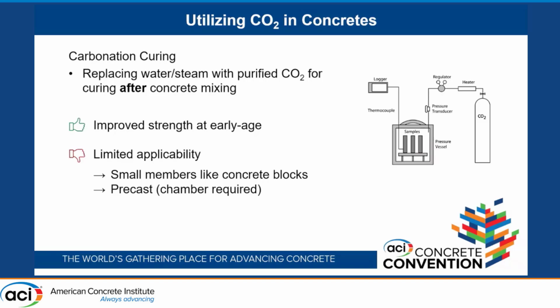Now, there are a couple of different ways that the industry utilizes this CO2 sink. The first way is through carbonation curing, where the curing water or steam is replaced with purified CO2 and is used to cure the concrete once it's been molded. This gives improved strength at early age stages for the concrete. However, it has limited applicability. It's used mostly for small, non-reinforced concrete blocks, and it can only be used for precast concrete, not ready-mix concrete. And when using precast concrete, it requires a chamber for the CO2 injection.